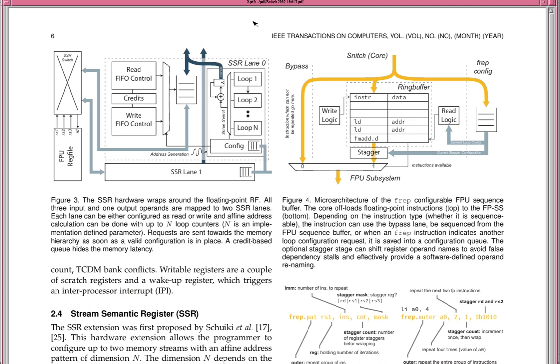So what they've done is time division multiplexing, so that you have 8 simultaneous banked loads and stores, and that way you can keep the floating point unit busy. The input uses tagged registers for a floating point multiply and accumulate, and the result does not go into the register file. It goes directly back out again to a second FIFO,